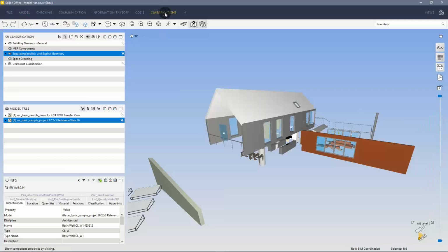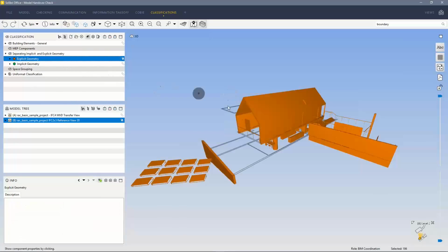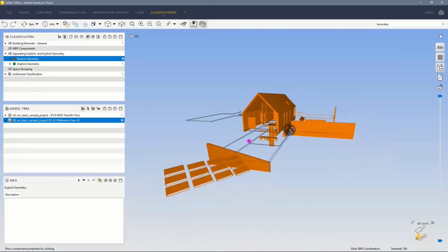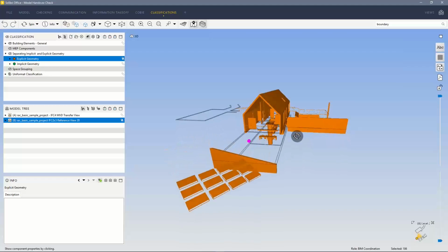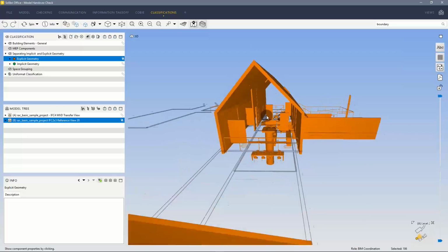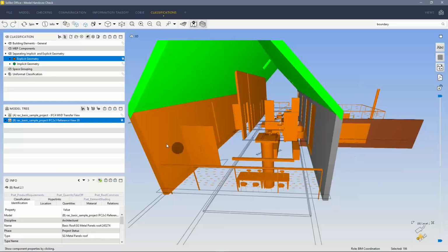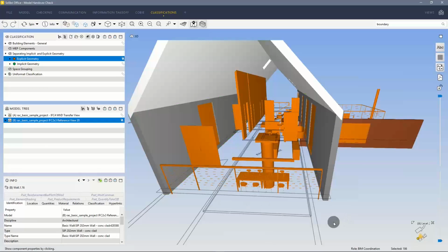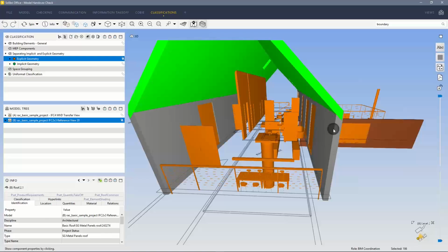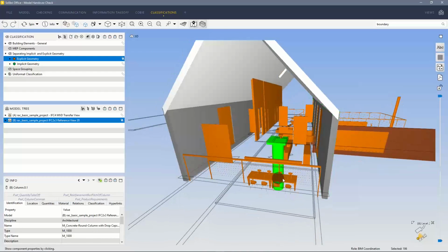So that's that. Now, just to make it easier for you to identify those two elements, I've also built a way to separate the two. Within that model, what I have in here in orange are all the elements that are built in the IFC with explicit geometry. And the reason why that is important to me is that I will expect to have all of these elements coming inside Archicad either as objects or as morphs. But they will not be, say, roofs or walls, or a column like the one down here, and so on.